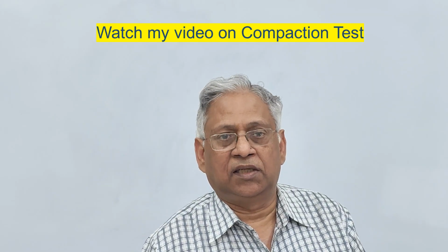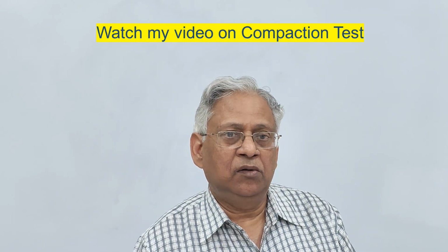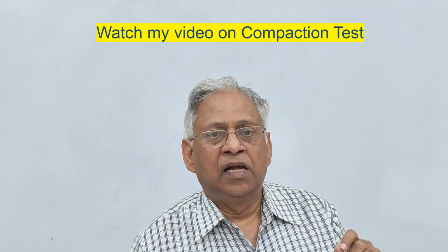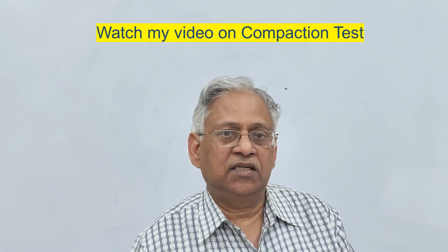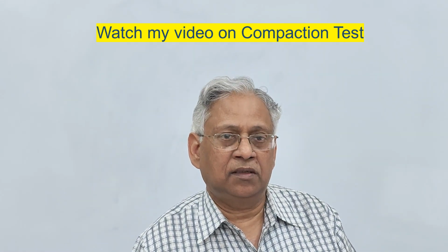the CBR test is conducted generally at optimum moisture content and maximum dry density, and therefore it is important to determine the OMC and MDD using the Proctor test. In case of low volume roads, we use light compaction, and in case of high volume roads, we use heavy compaction. It is explained in part 7 or part 8 of IS 2720 how to conduct the Proctor test. I have uploaded another video on the Proctor test, and you can watch that video to understand how we determine the optimum moisture content and maximum dry density of the soil.